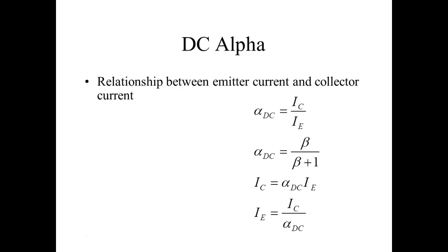But usually power amps are made of multiple stages. If you want 400 watts, you can't get 400 watts out of one transistor. So you go through one transistor amplifier to get so many watts, and you take that and feed it into another one and feed it into another one, and you keep getting more power until you get out to the final stages. Because your big power transistors require a lot of current. If they've got a beta of 30 and you're trying to get 15 amps out of it, you understand? That means you still have to put a lot of current into them, even though you still get a gain.